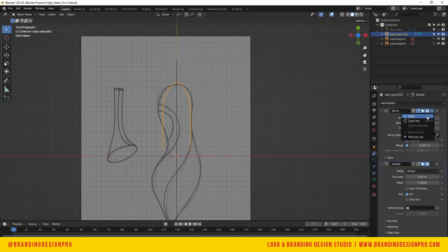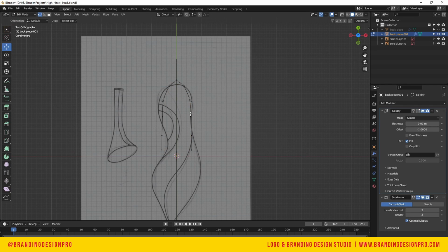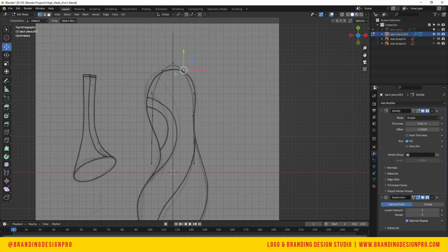From here, you're going to tab, go into edit mode, and hit Control-7 to be on top. Make sure you're on the top view. You're going to select the back vertices, hit E to extrude it forward. And then select the 4 vertices and hit F to fill. Select the opposite side, the 4 on the opposite side, F to fill. Take that middle vertices, extrude it.